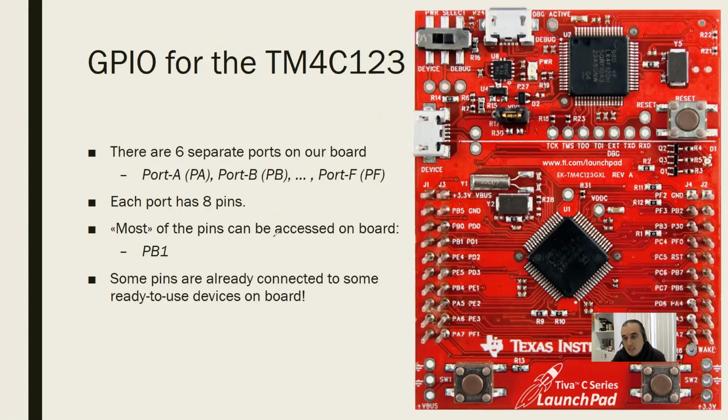What is nice about this card is you can connect anything to these ports. For example, a 1-bit sensor, a temperature sensor. When the temperature is high, it provides 5 volts. When the temperature is low, it provides 0 volts. When the temperature is in between, it gives values from 0 to 5 volts. That's an analog sensor that you can connect, or a digital sensor. Or you can connect an on-off switch.